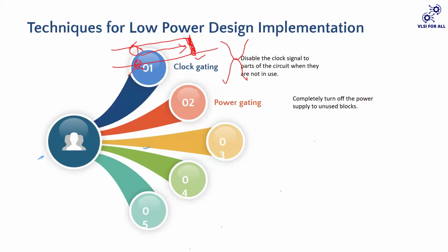the specifications, the requirement for the VDD is low for the CPU as compared to the GPU. Okay, so the concept is that we will use some voltage for some chiplets, and something different for others. So there comes this concept of multi VDD. Power gating and multi VDD are the ones which help us achieve a lot of good improvement in low power designs.